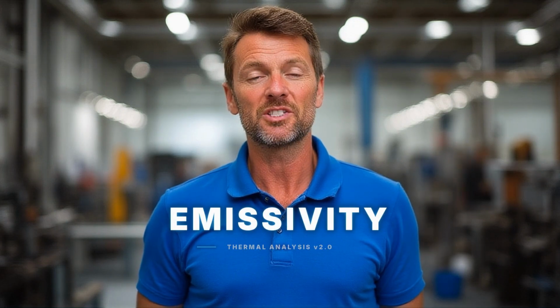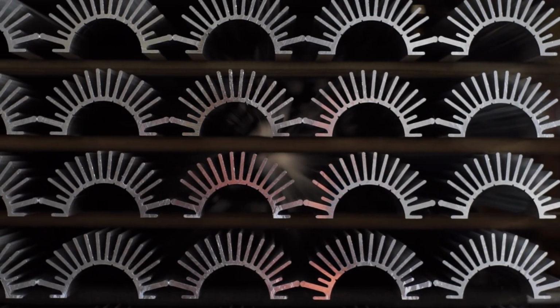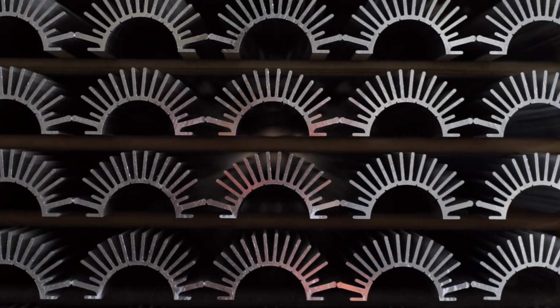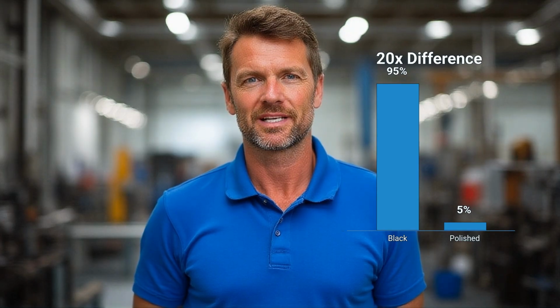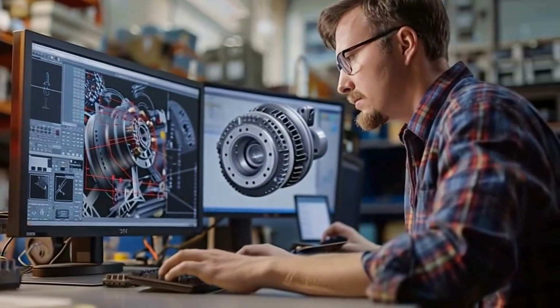The other variable that changes everything is emissivity. A black anodized aluminum surface has an emissivity around 0.95. It radiates heat extremely well. Polished aluminum sits at roughly 0.05. Same material, same temperature, but nearly 20 times less radiative output just because of the surface finish. That's a massive design lever most people overlook.